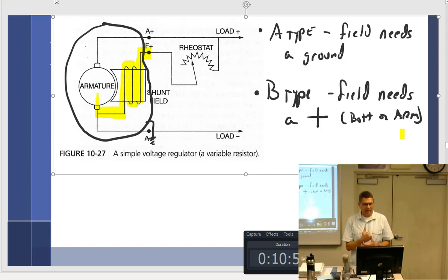I don't think the person working on them quite understood the difference between an A and a B type. Inevitably we would get the engine all put together, put the new generator on, fire up the engine, and everything worked great except we have no volts and no output on the amps.